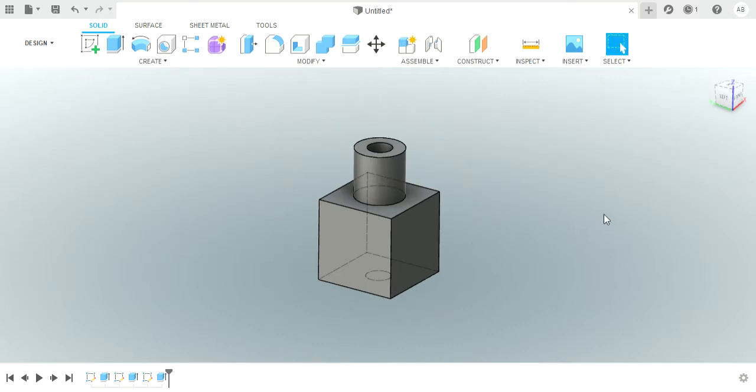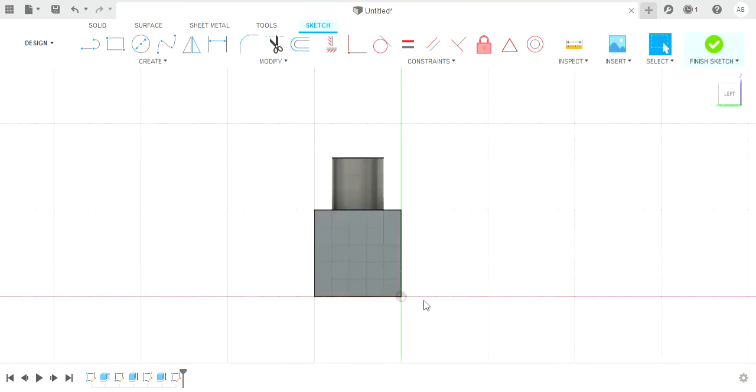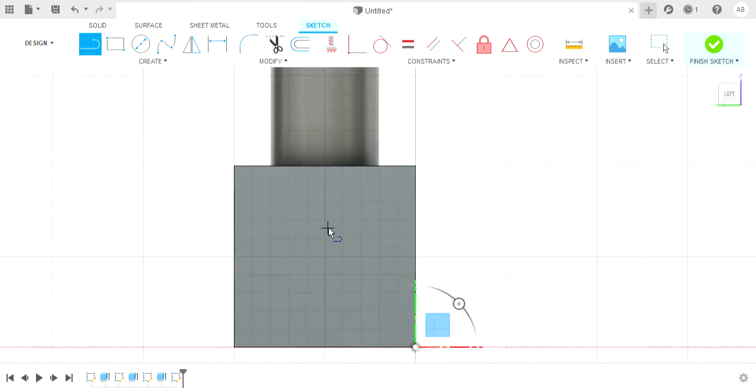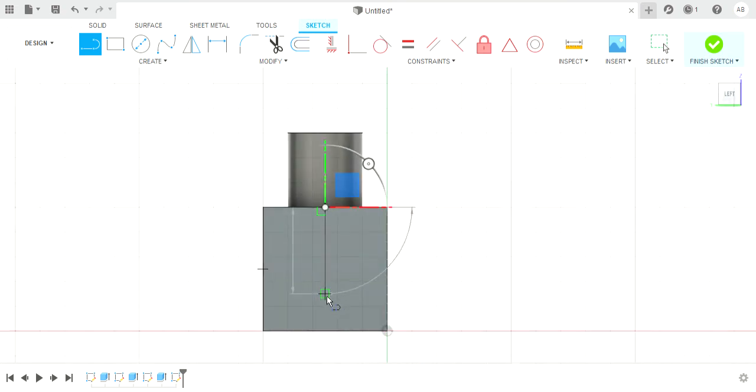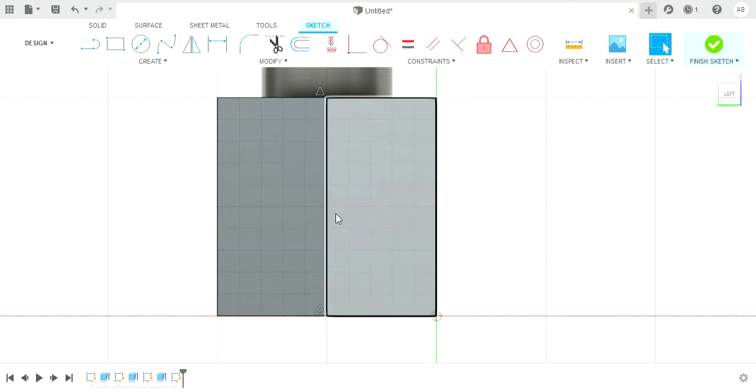So we're going to create a new sketch, and you can pick any side of this object because it's symmetrical. You can pick any face, create a new sketch. Prefer to look at it in 2D. Then we're going to draw a line on this surface here down the middle of this face. Okay, now when it loads, if I click on this face here, this line here, and highlight it so it's blue, on the left hand side we've got this sketch palette.